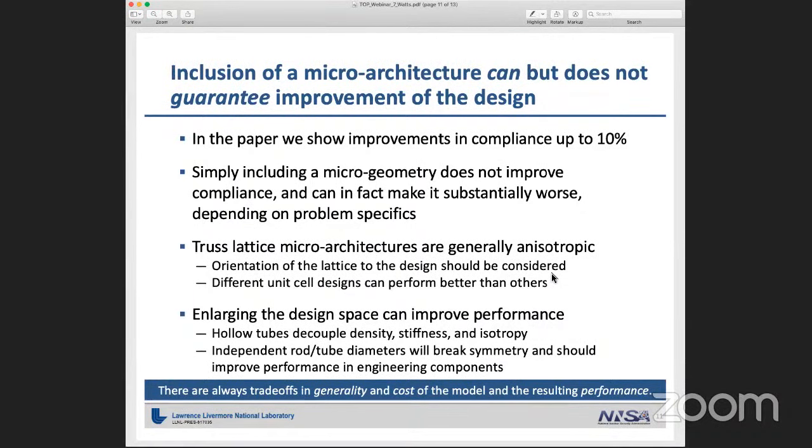Getting to the conclusions, if you move to these types of microlattice materials, you can improve your compliance design results modestly. It's not a huge improvement. It's also not a guarantee that if you have a microstructured material that you will improve your design. We showed some that are essentially a wash, that were no better than just doing SIMP design. And depending on how you limit the microstructure you're considering, you can actually make it substantially worse.